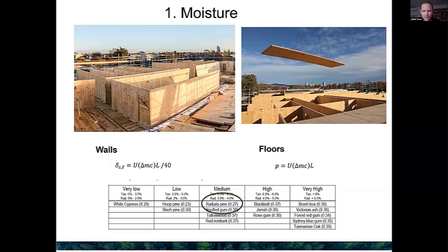Okay, so now zooming a bit more into moisture. These are some of the equations we can look at. The unit tangential movement to the grain is different for each species of timber. When it comes to radiata pine, which is what our CLT is made up of, and also a lot of glulam out there, it's 0.27.